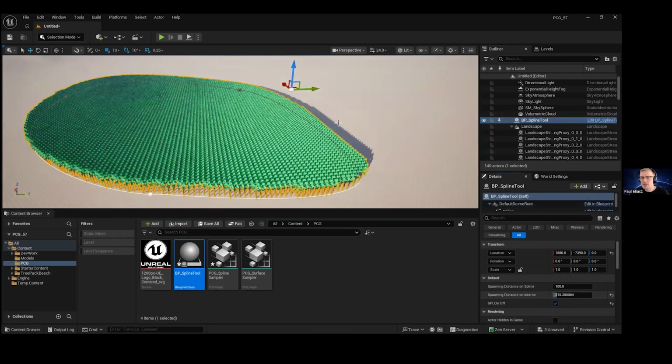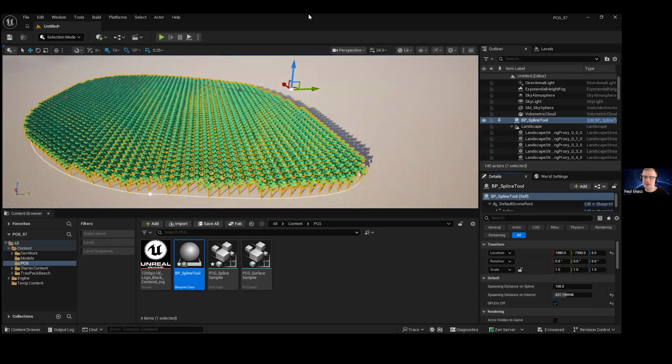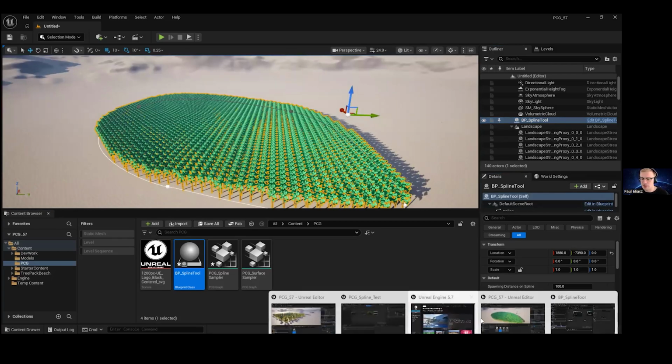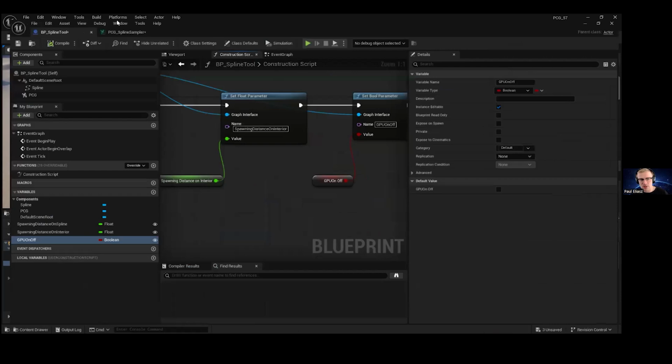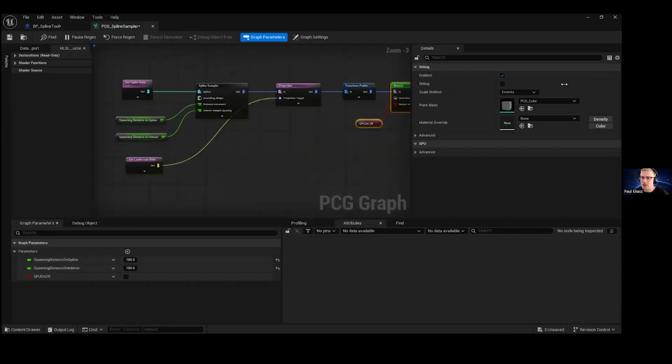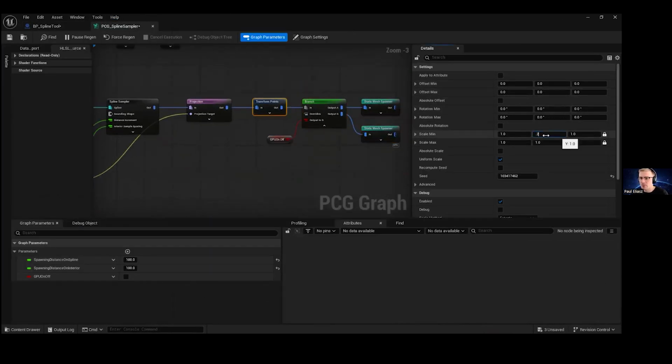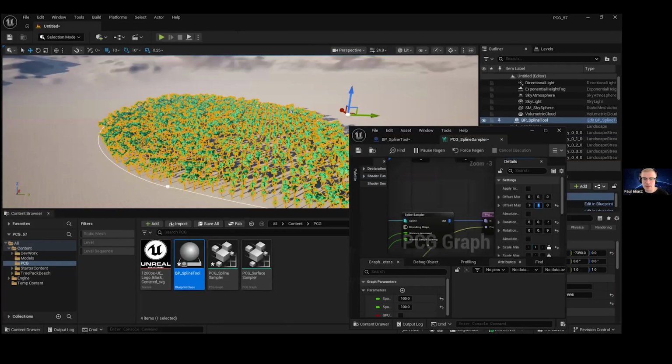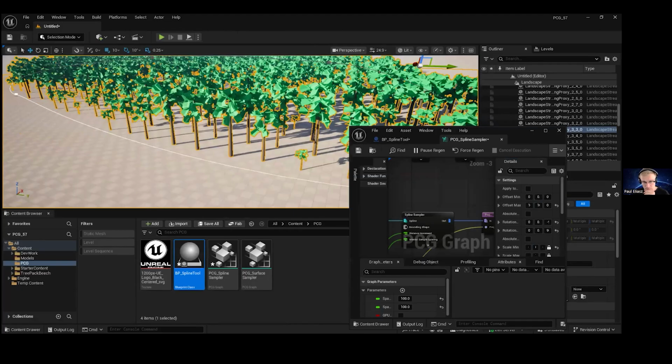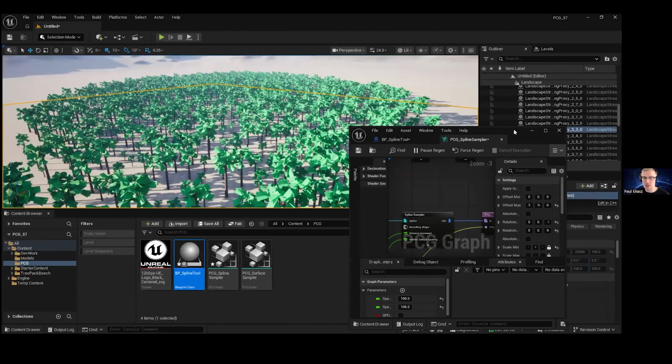Even though it looks very even, this is down to using the transform points. So if you wanted to change this, that's something you can do on this end. You can just go and change the formation here so it looks much prettier. I can set it to 0.25, change the rotation, minus 90, minus 90, and then 90 degrees. And then maybe change the offset to like 100 difference. I see there's a bit of the forest there. It looks different now, so it's cool. That's something that changes the variety of random placement of the static meshes in space.